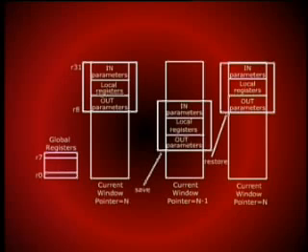R0 to R7, written as global registers, indicate and store the values of global variables. And then the current window, for example, at the top addresses from R8 to R31, the 24 words store.